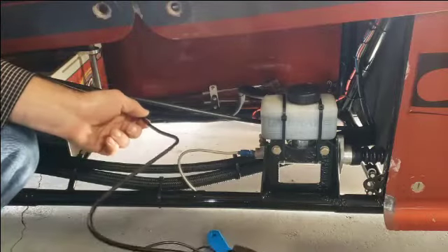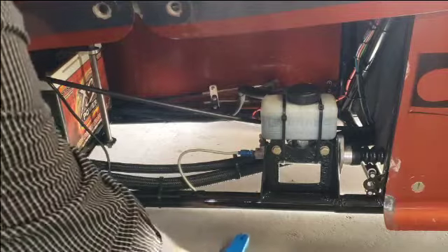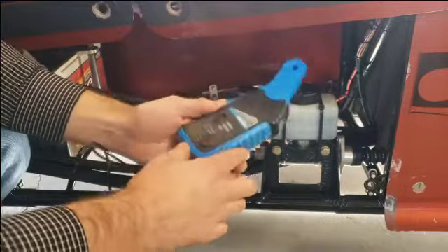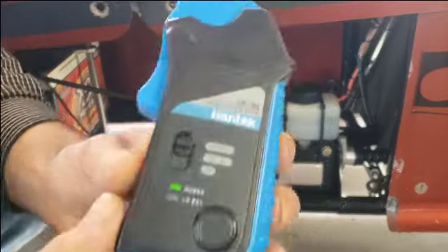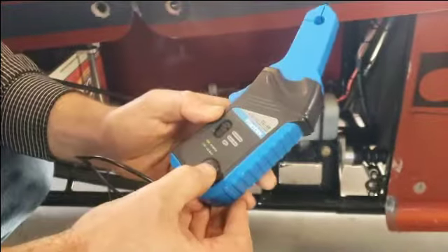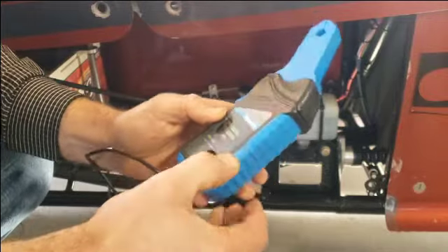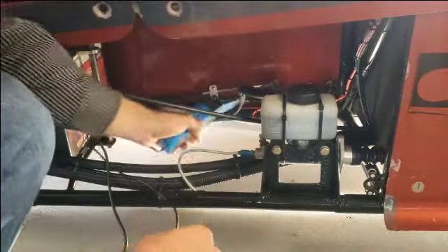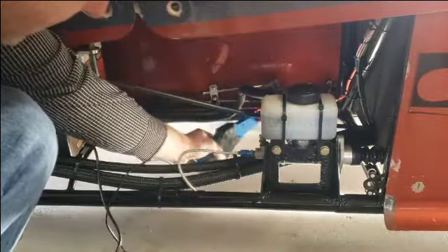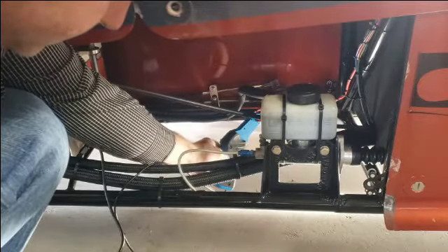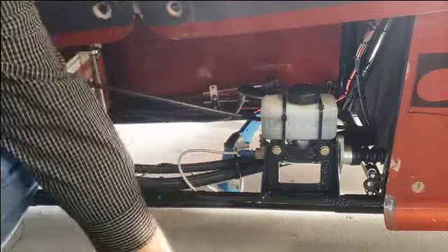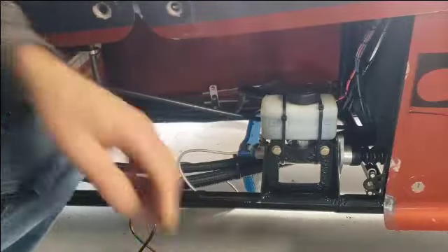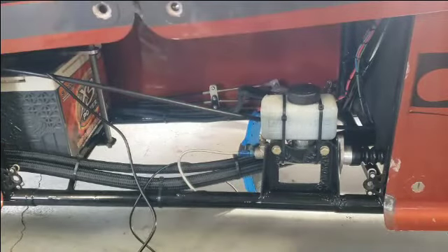Now we can't measure current flow directly because remember, current flow is a measurement of the flow of electrons. So what we do instead is we measure indirectly using a current clamp. A current clamp takes advantage of a property that we talked about earlier, that as electricity moves through a wire, it generates a magnetic field around that wire. What my current clamp does is use that magnetic field and produce a voltage relative to that magnetic field that can then be displayed on my screen.